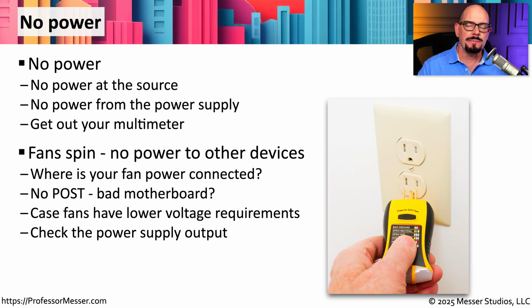If the fans are spinning but we're getting no video when we start up, then it's probably a POST error, which means your motherboard itself could be bad or the video card of your device could be bad.